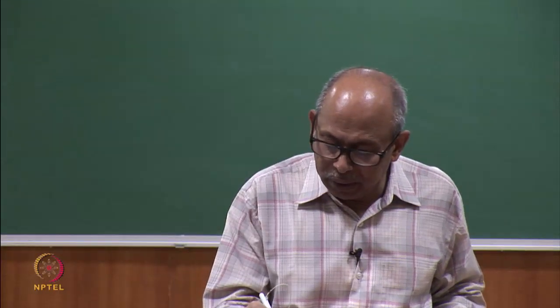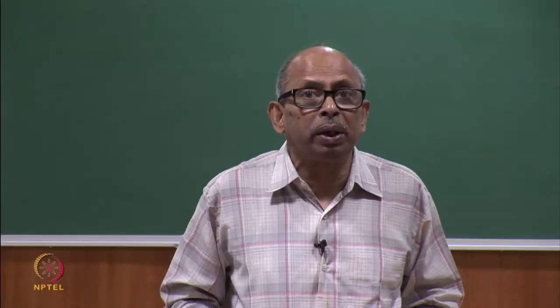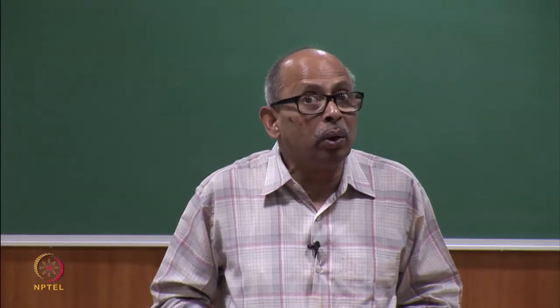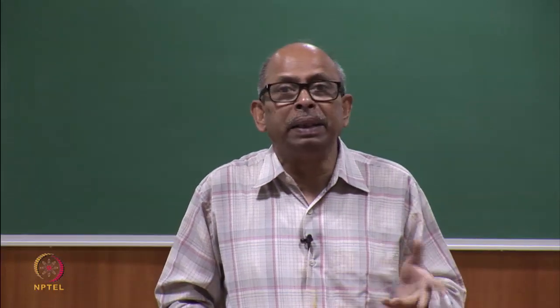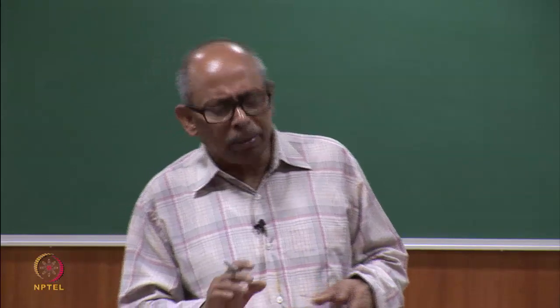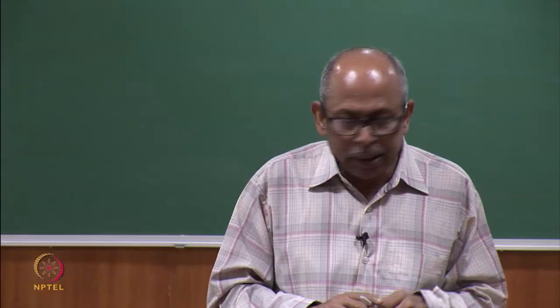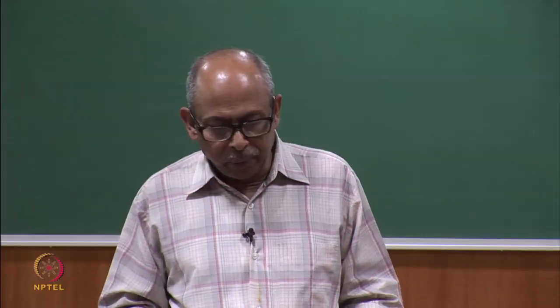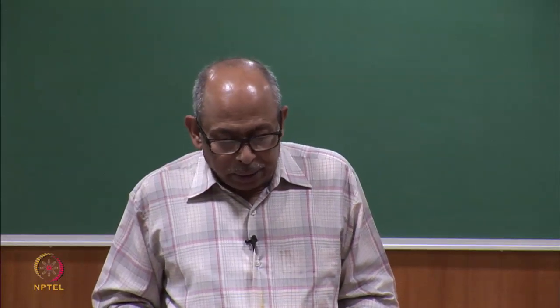Similarly, strength at the surface will be lower compared to the core. Core concrete is better. So while selecting locations, in columns you should not take all the testing locations at the top of the column or the bottom of the column, because then you are biasing them. So either randomize them or choose depending upon your requirement. I will come to that again sometime if I talk about a case study. So, that is what it is.